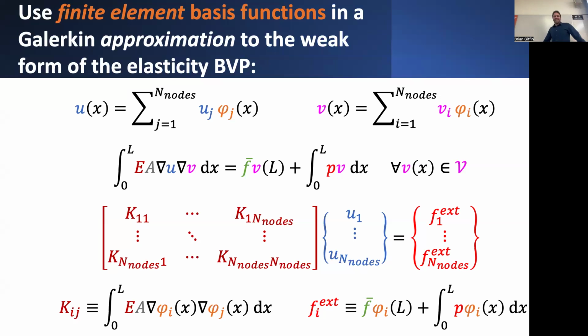Now, this is where things get hairy, because certainly we could go about computing some of these integral expressions that involve derivatives of the nodal shape functions with respect to x, products of those shape function derivatives integrated over the domain in order to come up with these individual contributions to the stiffness matrix. But we have to take all these integrals, which is not nice. Obviously, if you have a lot of these different entries, and potentially as many entries as you have unknowns squared, then that's a lot of integration that you have to do, which is not something that you want to spend your time doing.